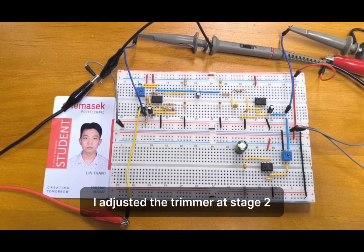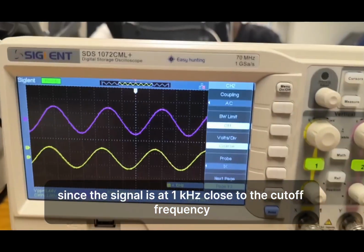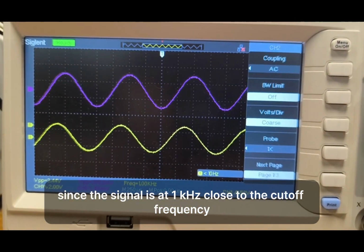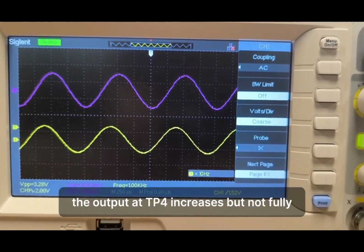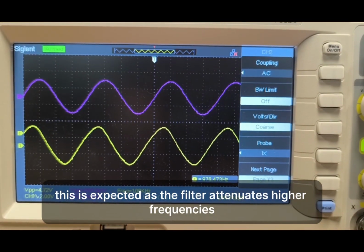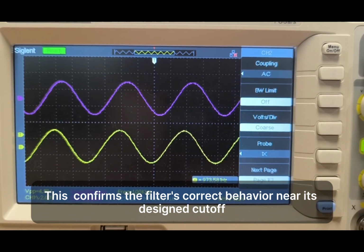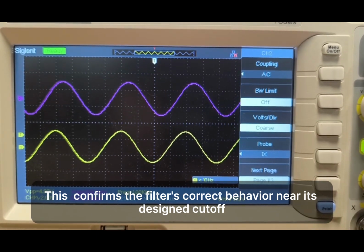I adjusted the trimmer at stage 2 to increase the input signal. Since the signal is at 1 kHz, close to the cutoff frequency, the output at TP4 increased, but not fully. This is expected as the filter attenuates higher frequencies, limiting the gain. This confirms the filter's correct behavior near its designated cutoff.